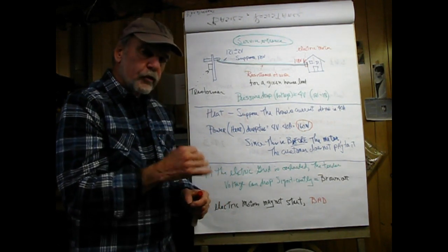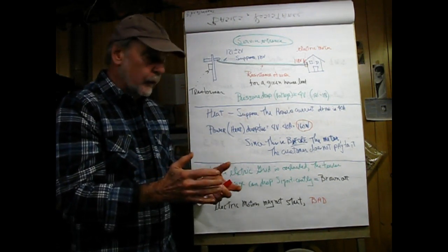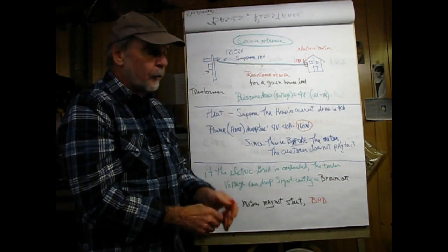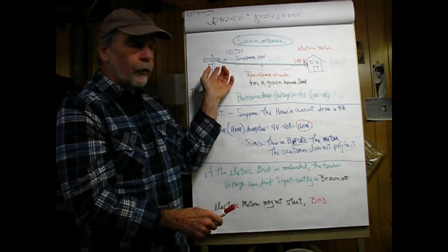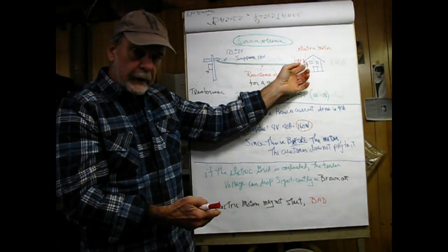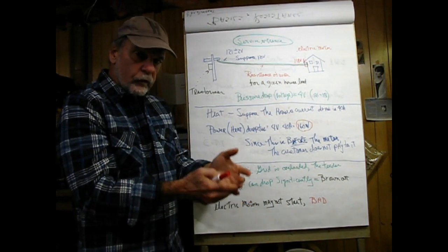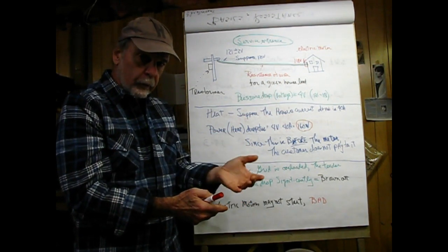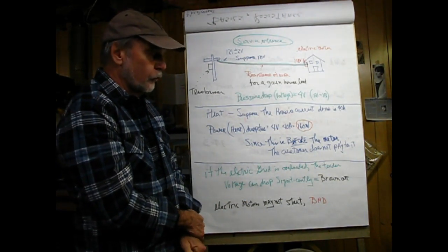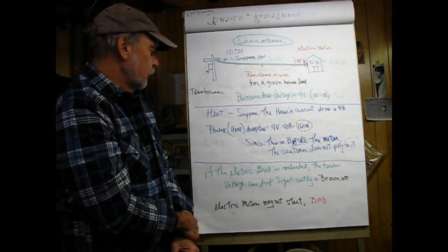And the reason is the starting surge current of the motor or the water tank's heater element causes a voltage drop in not only the service entrance, but all the wires leading from the transformer, I could theoretically say back to the power plant, through your fuse or circuit breaker panel, through your house wiring and so forth. Voltage drop, lights dip, the motor starts up, current drop, the current through the motor is reduced, and then the voltage drop in your house basically is returned somewhat to normal. So we can see that we lose voltage in this case, which would be 4 volts.